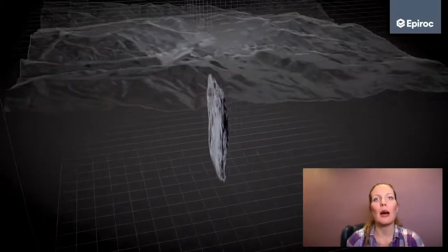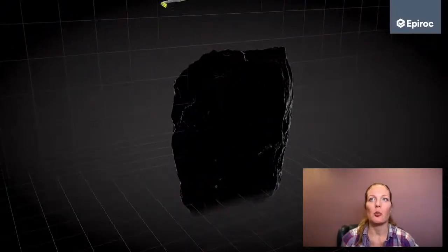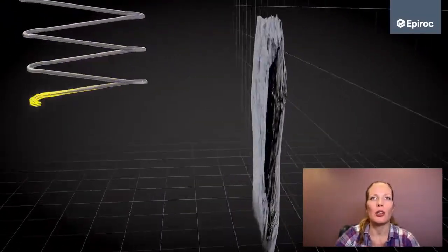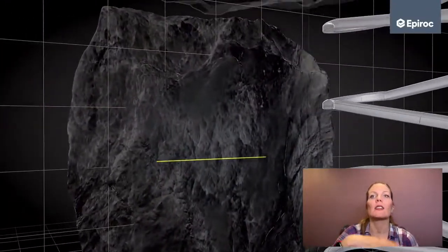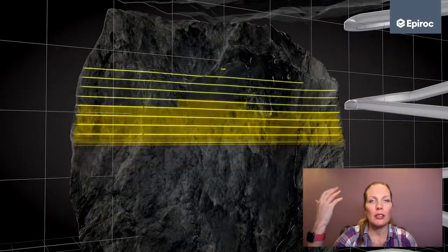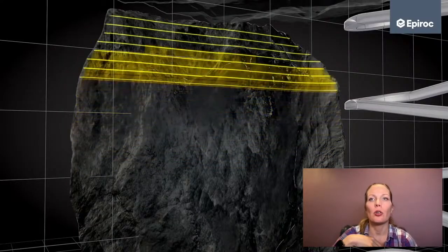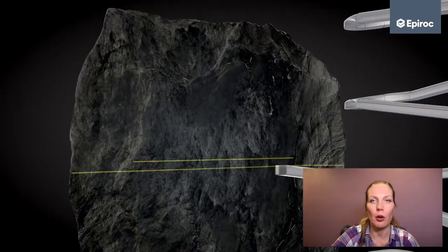In cut and fill mining, an optimized stope isn't just a geometric shell. It represents a full cycle of repeating stages: drilling fan patterns for each slice, blasting, mucking and drawing, cleaning, placing backfill, waiting for it to cure to the required strength, and then shifting equipment to the next slice horizon.